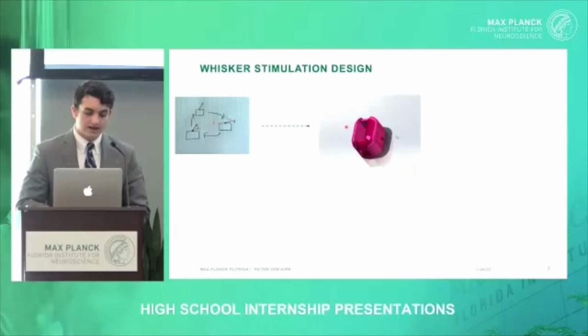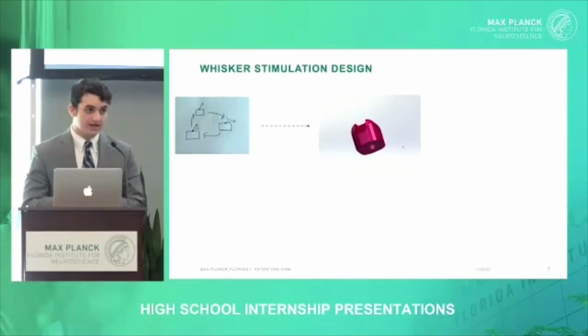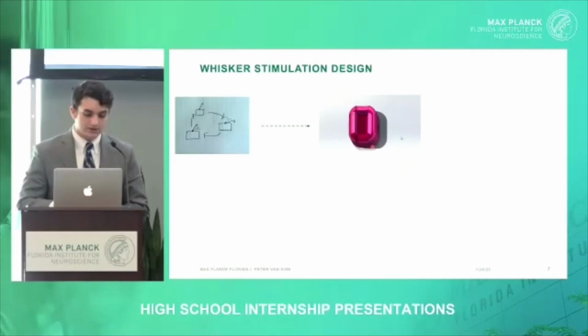And then I made a case in SolidWorks. SolidWorks is a CADing software, computer-aided design. As you can see right here, I have a hole. This hole is used for a zip tie, so you can actually fasten this case to the microscope. There are also curved edges on this case because if you have any experience with 3D printing, if you have a solid edge, it's very difficult for a 3D printer to print this. So it takes more time. By having these curved edges, it reduces the printing time.